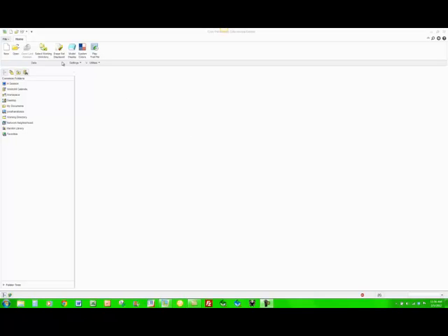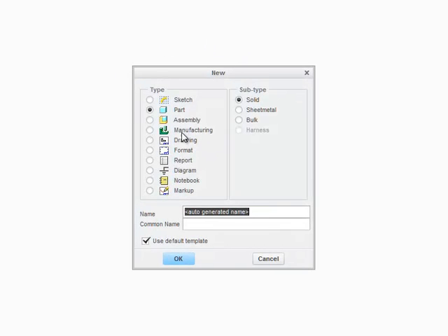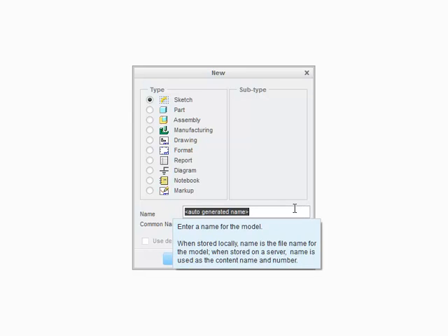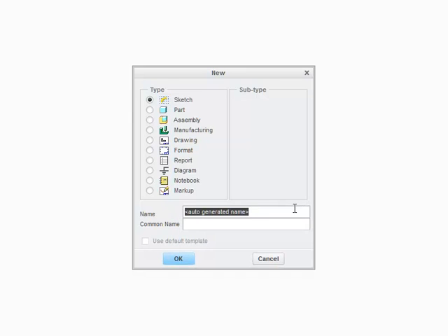So the first thing we're going to do today is hit this new button. A prompt will come up. You're going to select sketch, and I like to name things so that they'll be easy to find. So today I'm going to name this 2 inches underscore 1 inch underscore 1 underscore 8. Now the 1/8 is 1/8 thickness. Helps me remember that. I'll use this sketch.